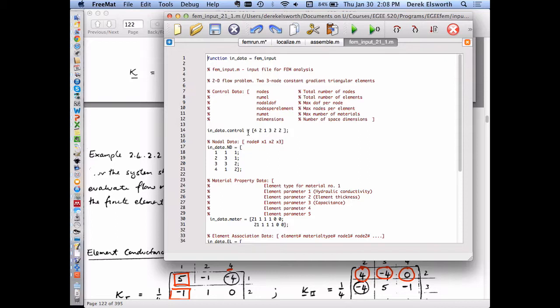And so what it needs to know is that it has heads or fluxes at each of these nodes. So this is 1 degree of freedom. So you'll see the shorthand in this, DOF is degree of freedom. You can see that throughout finite element stuff. And so the information it needs to be able to solve this problem is just this. How many nodes are in the system? 4. And so if you look down here, that's exactly what this is. So these terms here are just these values.